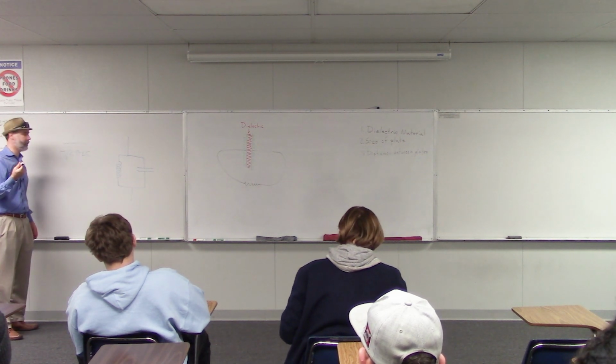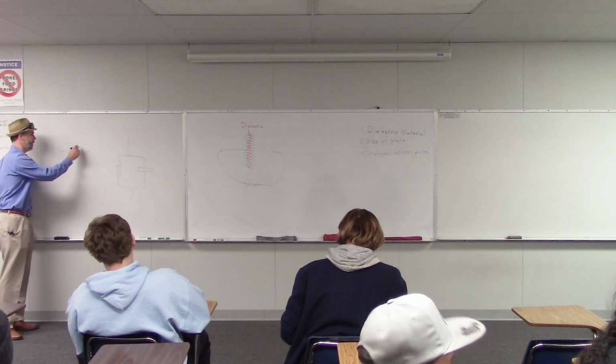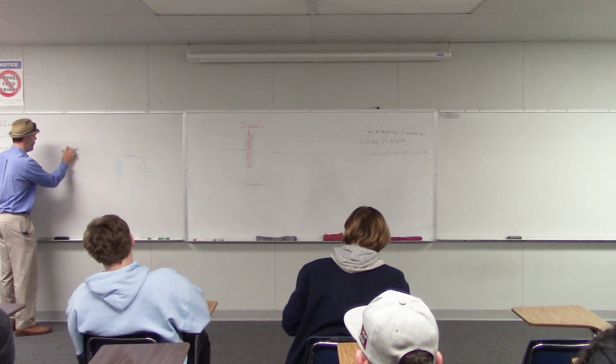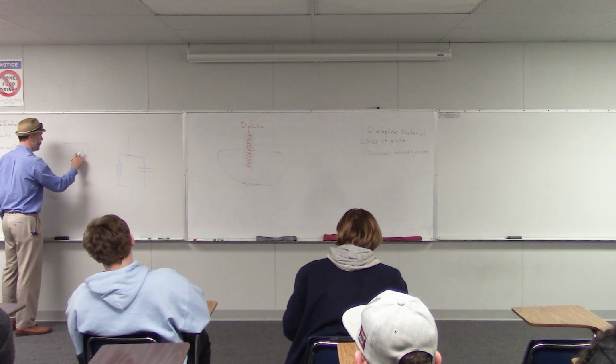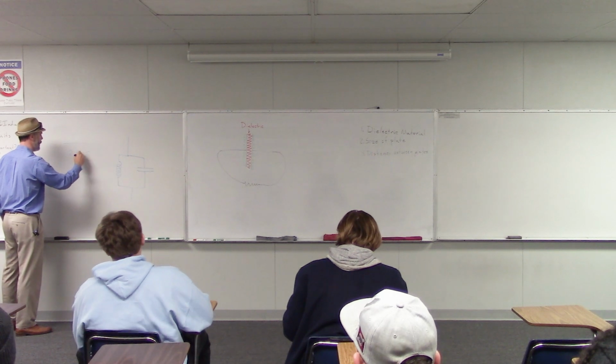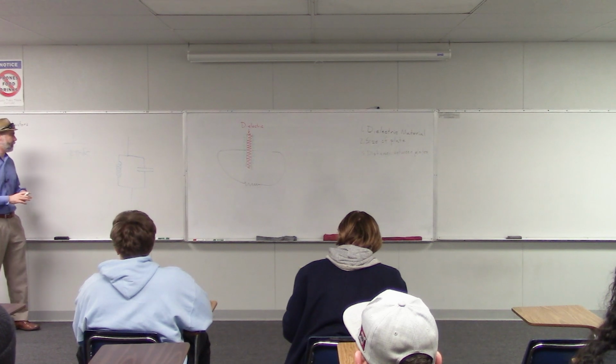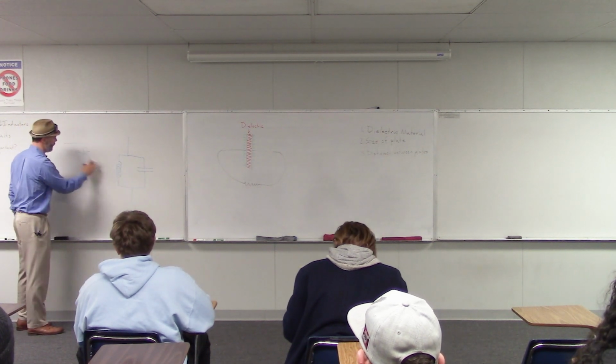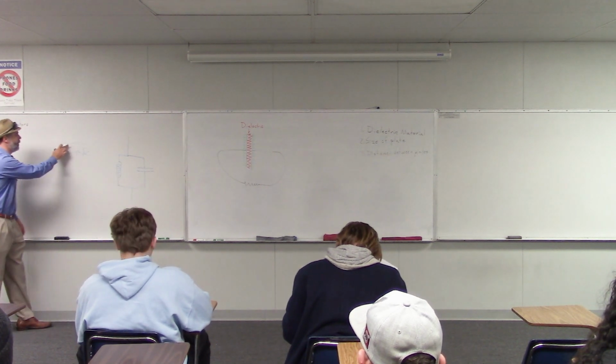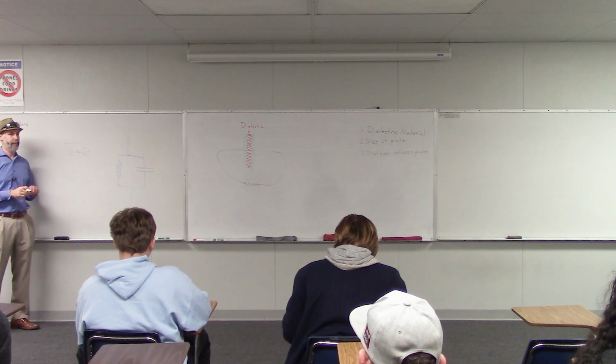Am I getting close? Do you know? 1 over 2 pi square root LC. Oh, okay, thank you. If you don't use those every day, you forget about them. Sure. Yeah, 1 over 2 pi square root of LC. So that would be where L is the inductance and C is the capacitance. That would be the resonant frequency there. Thank you. Sure.